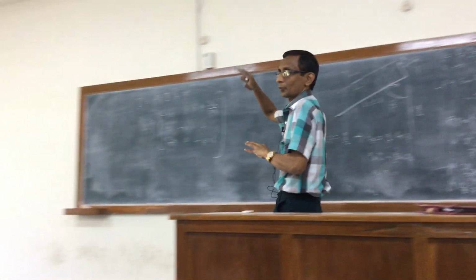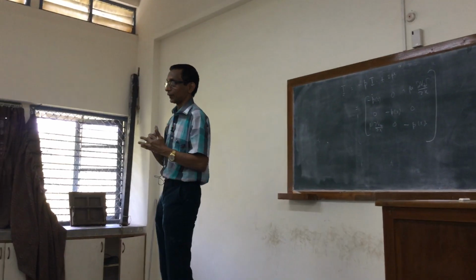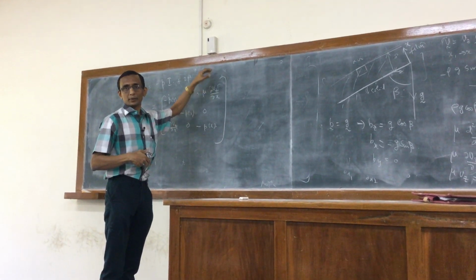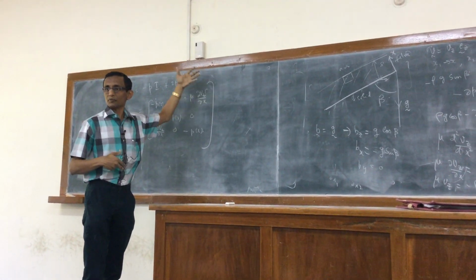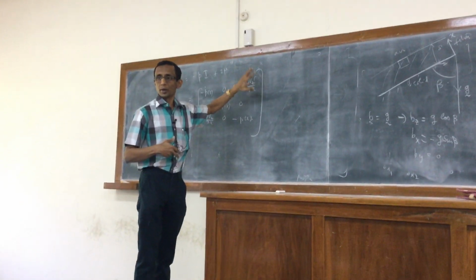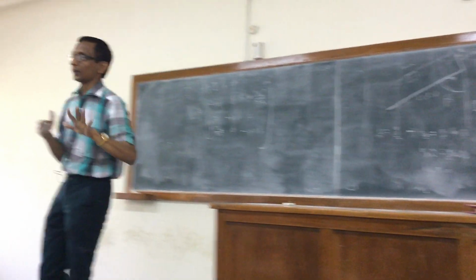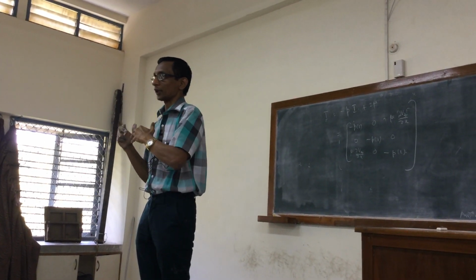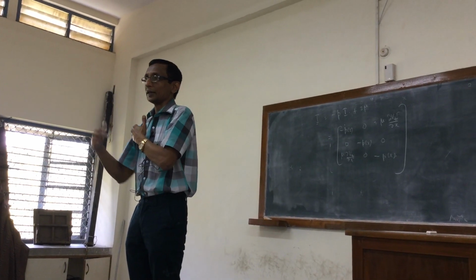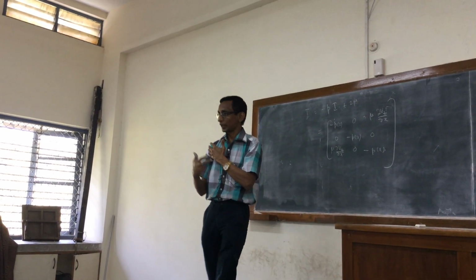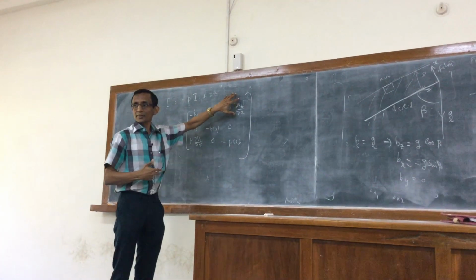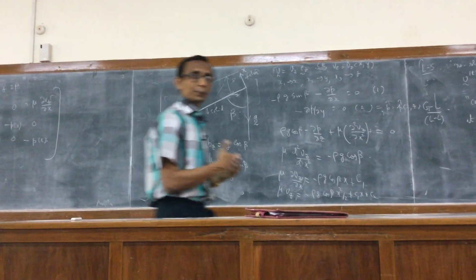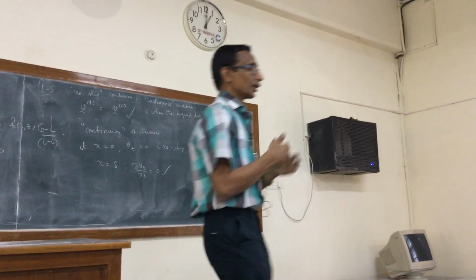It doesn't mean that mu is 0, because for the air viscosity is 0. We are not looking at whether there is a velocity profile or what kind of flow the air is undergoing. But clearly the shear stress would be 0, whatever the air might be undergoing, because our focus is only on the liquid. Air comes into play because it is at the interface on one side of the liquid. So if the shear stress experienced by the air is 0, then the shear stress, due to the continuity of stresses, experienced by the liquid at the interface must also be 0.